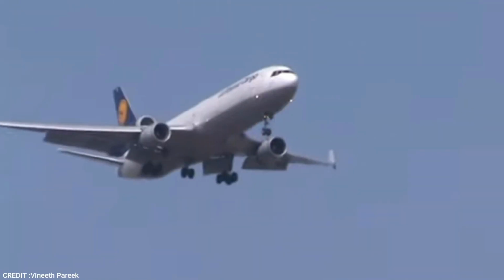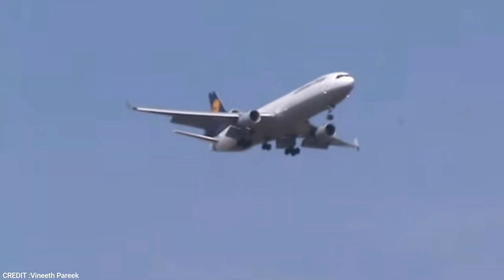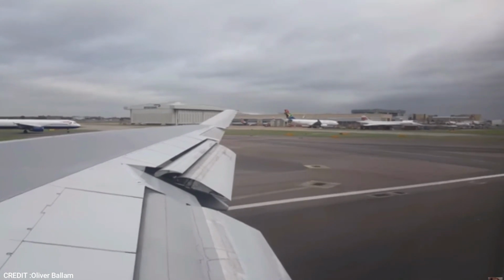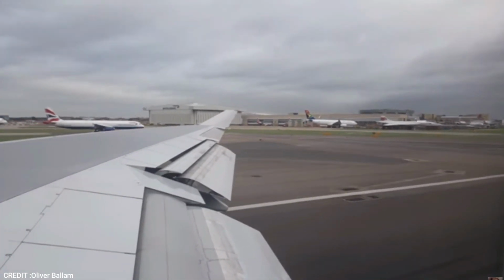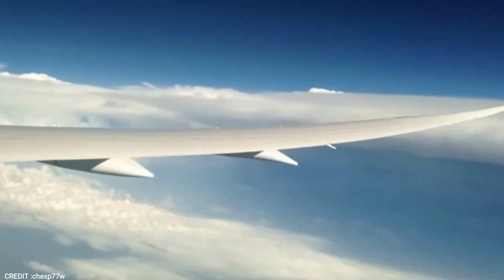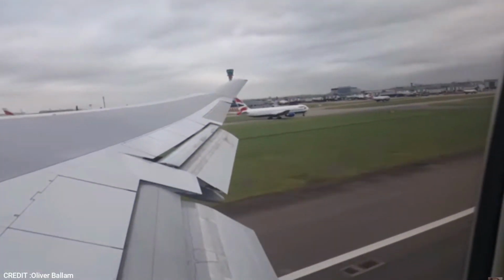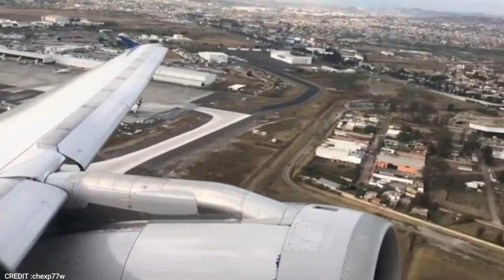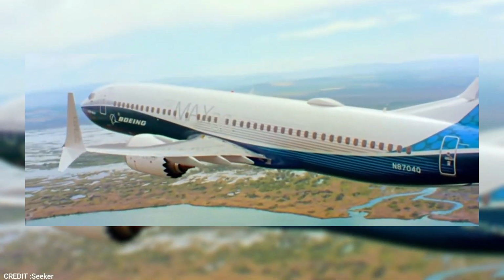The lower pressure above the wing causes this circulation, and it will be counterclockwise if the wing moves towards the left and air flows over the wing towards the right. To balance this rotation, a counter-rotation of the airflow is set up over the wing, where the airflow circulates in a clockwise manner. This creates pressure differences from the top and the bottom of the wing.